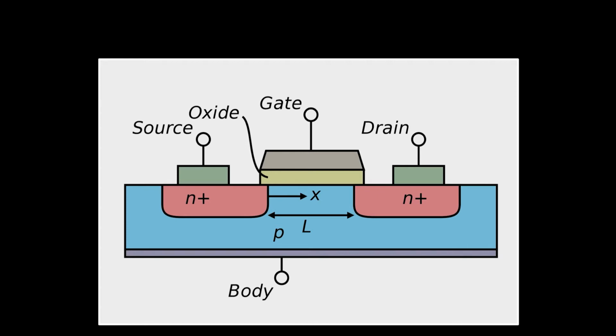To summarize, the gate to substrate voltage, and since the substrate's normally connected to the source, we normally say the gate to source voltage, although technically it's the gate to substrate voltage, determines the resistance between the source and the drain. Just think of the gate to substrate as a clamp on a piece of pipe. It can clamp down on the pipe to limit the flow of electrons, or it can open up and allow as many electrons as possible to flow through the channel here.